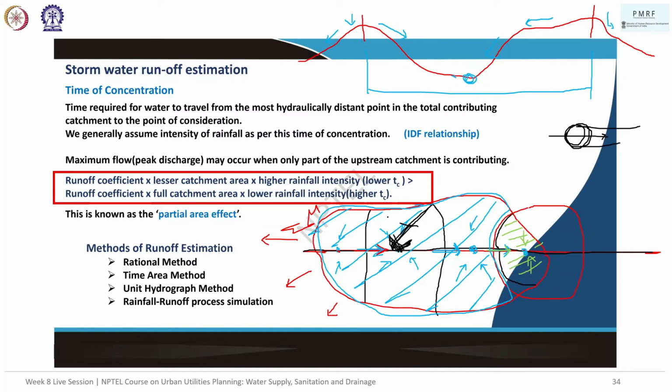So essentially, three factors. For example, one is the slope, one is the permeability. Say a lot of water falling in this area is actually going inside the ground. It's not even coming to the water body. Versus in the green area, say it's all rock, and say it is very, very steep, which means the amount of time that this water is going to take to reach this point is going to be very quick, right? So the flow at this point will be much higher.